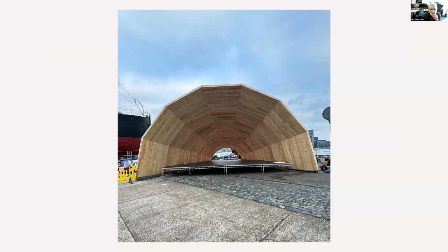So this is it in its finished iteration with the staging. We can't see there is the cables that run across the bottom. There are quite strong forces at the top. I think it's about 10 kilonewtons, and halfway down it's about 4 kilonewtons of force in like a moment connection. And then the cabling across is what stops the building pushing out. Here we couldn't go deep with the foundation because we're working on a car park. We had to work with something in a slightly different way.